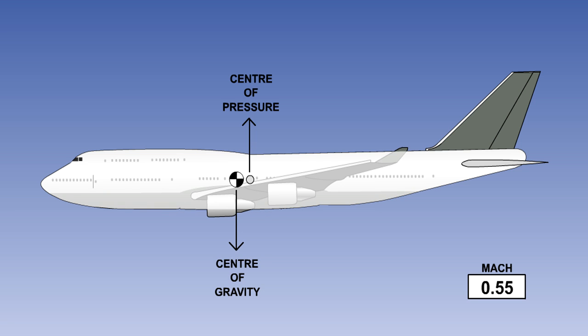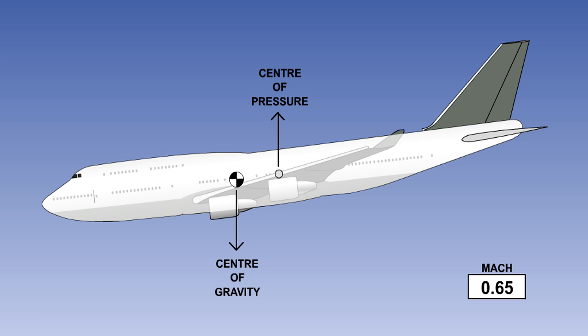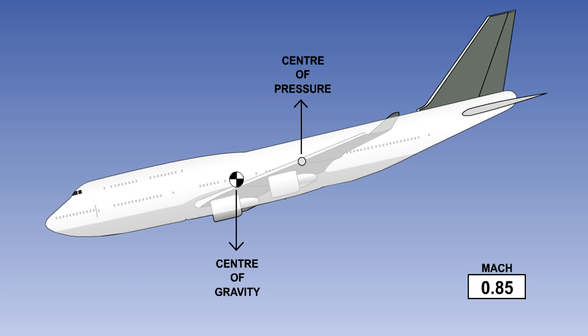On most large turbojet aircraft, the wing centre of pressure moves rearward as the aircraft approaches high subsonic speed, and this produces large nose-down pitching moments, known as tuck-under or Mach-tuck. It is essential that the aircraft is fitted with an automatic system to correct this change in pitch attitude. Such a system is known as Mach trim, and is designed so that it will operate whether or not the autopilot, or some other method of automatic flight control, is engaged.